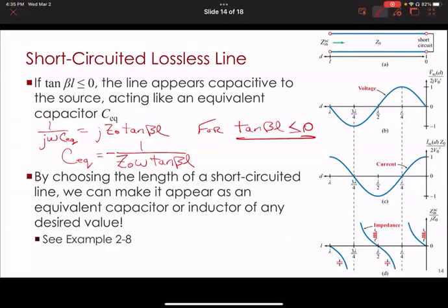What I'm telling you is, if you're doing a circuit design at a frequency or wavelength where transmission line concepts are kind of in the ball game, like they're at play, and we know how to do that because we have our rule of thumb, right? We have a rule where we said we do the ratio of L to lambda, right? And if it's bigger than a certain number or less than a certain number, that tells us whether transmission line concepts need to be taken into account or not.